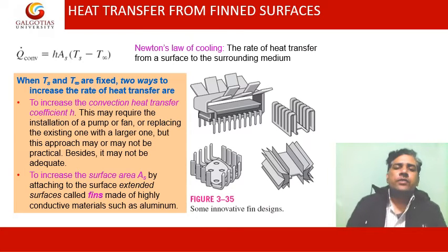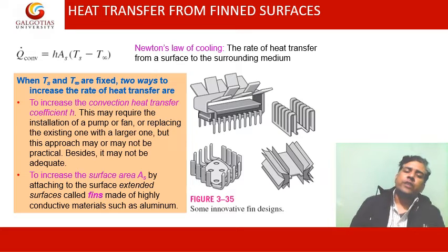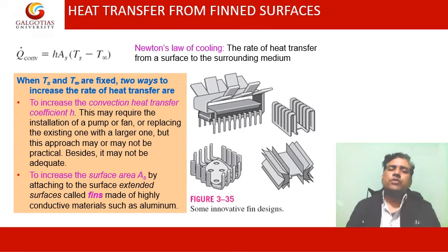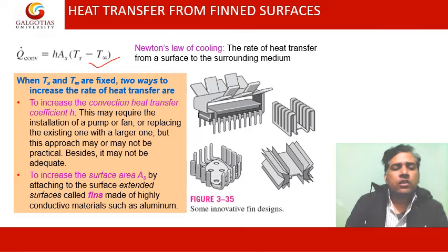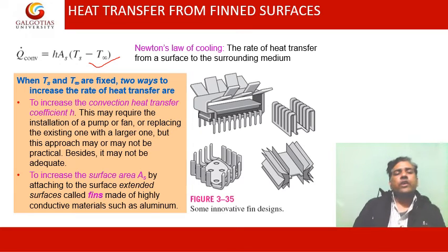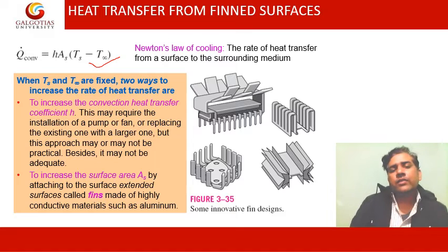Now, heat transfer from finned surfaces. As we have seen in many of our home appliances, sometimes we add some sort of fins, or some extra fin-type material, on the surface to increase the heat transfer rate. From Newton's law of cooling, we know that heat transfer by convection is given by this formula, where Ts and T infinity are fixed.